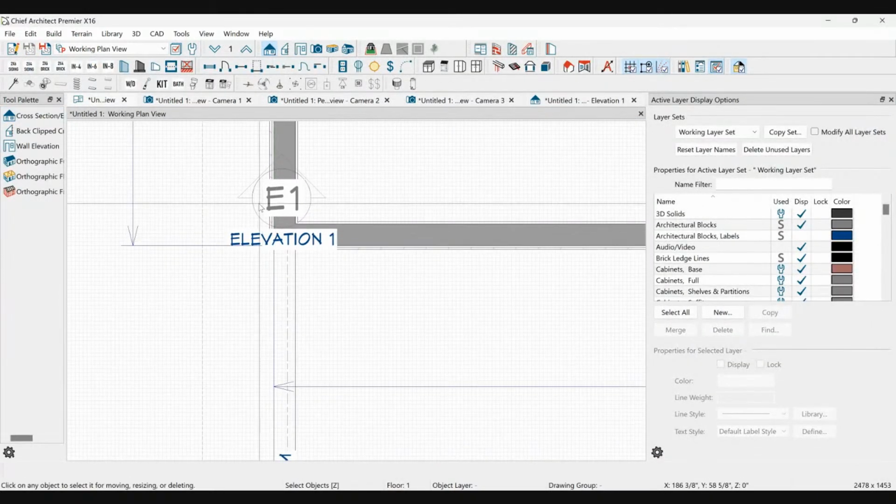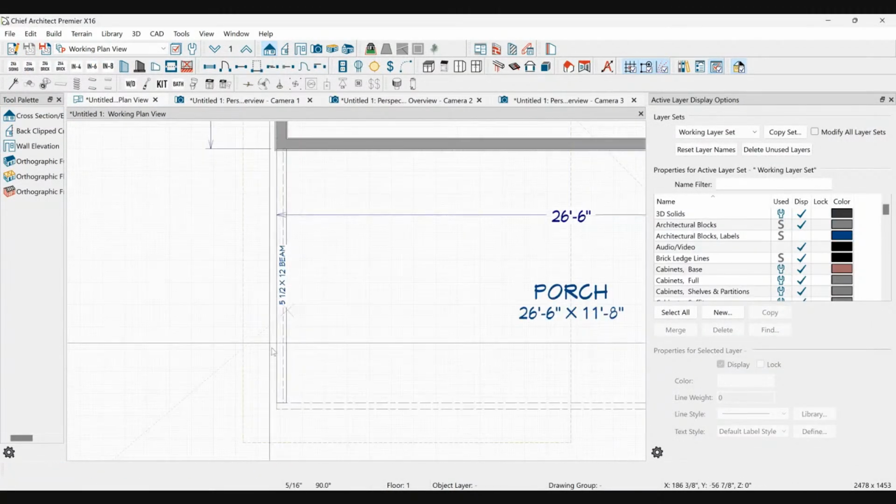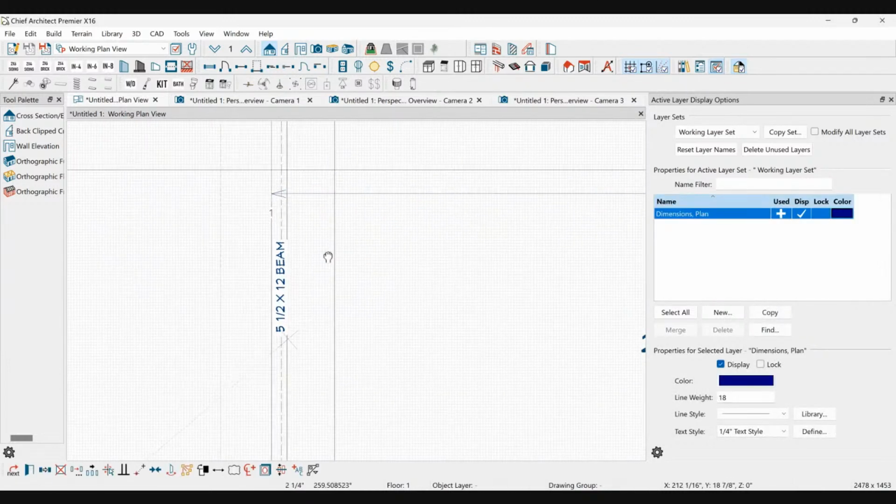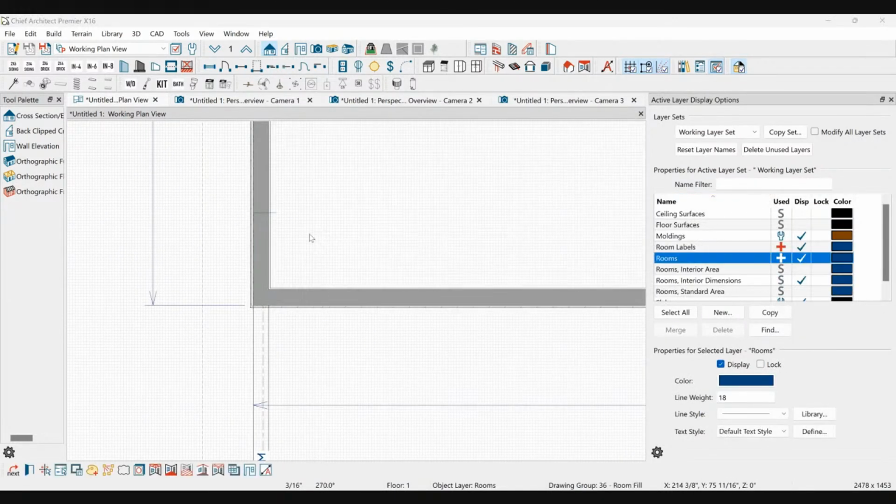So if we got rid of this elevation, we would see that this beam, if we opened up the settings of this room and said, hey, what's the structure? The ceiling is framed up to 109 and 1/8. Why is it 109 and 1/8? Well, it's because it's a 9-foot ceiling, which is 108 inches, and you add an inch and an eighth to the wall height because you're using pre-cut studs, and it's that way because it makes it easy to sheetrock. So that's the number. If you're trying to do the sheetrock pre-cut stud method, you're going to add an inch and 1/8 to your walls.